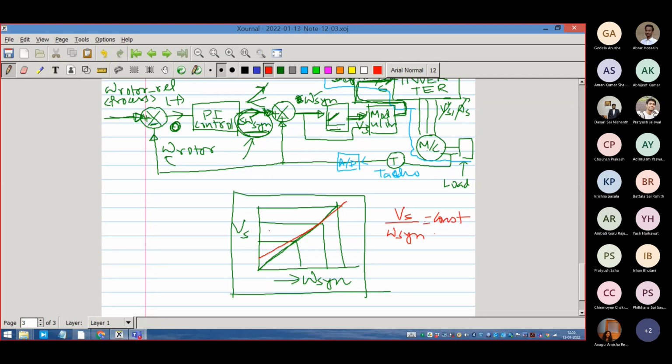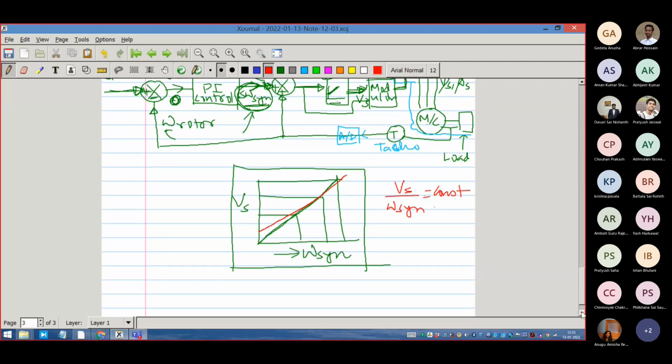So this will dictate what voltage we need to generate. And then when we know what voltage and what frequency we need to generate at the motor terminal, we have to generate the appropriate gating signals, that when I switch should turn on this switch or that switch. And that is done by a thing called a modulator. That is what I am saying, that is called a modulator.